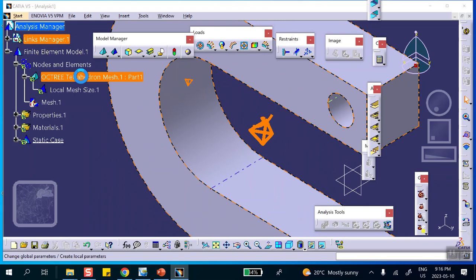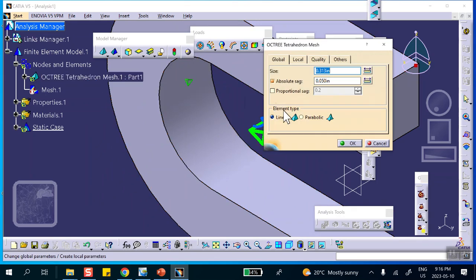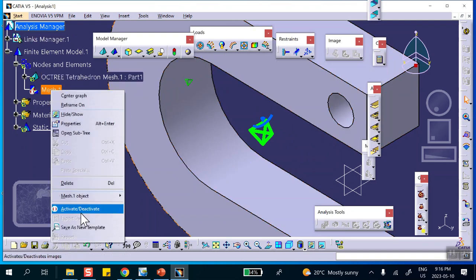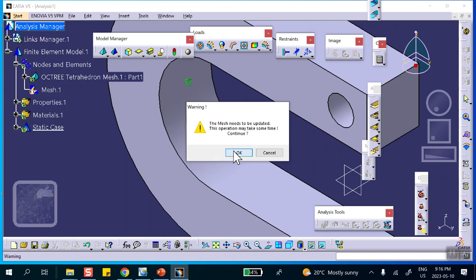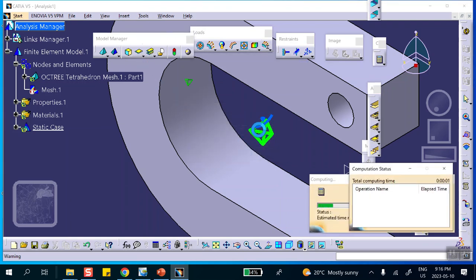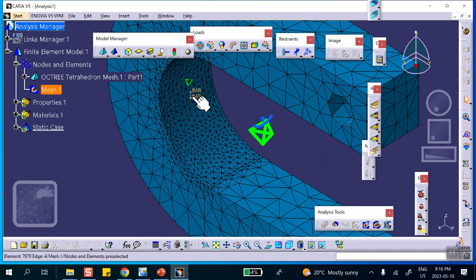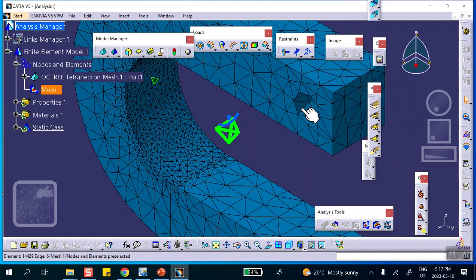By the way, our element is linear because of what we did in the first problem. You can always change that to parabolic, but right-click Mesh Visualization, and you're going to see roughly that kind of element everywhere except for that inside hole. You can see that. Okay. Now already it shows you that the mesh is really not good here. So actually, you know what I'm going to do?